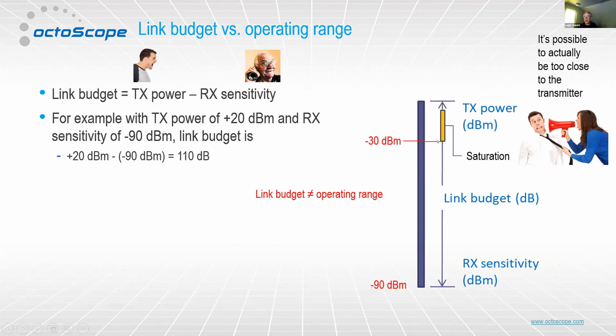So there's what's known as an operating region between the highest level signal that a receiver is built to handle and the lowest one. And with Wi-Fi, the range is something like this: -30 dBm at the top side, down to in the neighborhood of -90 dBm at the bottom side.